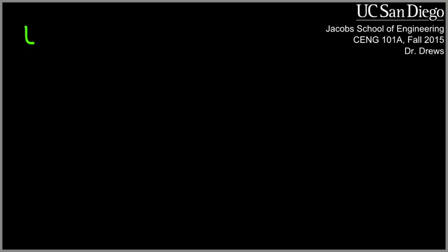Tau naught, remember, is the shear stress at the wall. So tau naught, we said, was defined as tau yx, or actually, since we're typically working in pipes, this is more like tau rz. This is evaluated when r is equal to big R, which is at the wall.